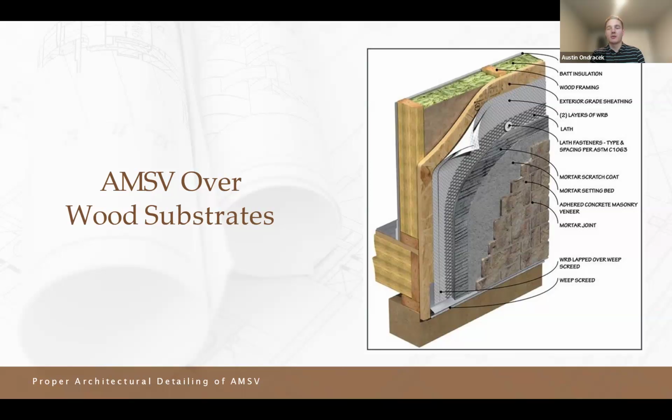And so, talking about the main factor when looking at a natural stone and anything adhered to any type of substrate, it's making sure water is directed away from behind it. You have the weep screed that can push that water out through that water channel, or a rain screen to help funnel all that water out from behind it if water does happen to get pushed in.